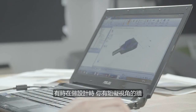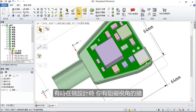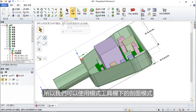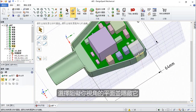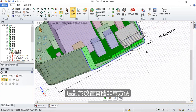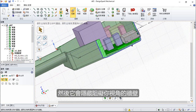Sometimes when making designs, you have walls that are obstructing your view of a component. So for instance here, we can't see the USB port properly in order to position it in the pin holes. So what we can do is actually use the section tool under the mode toolbar. And what we can do is select a face and it hides the wall that is obstructing your view of the object. And this is really handy for positioning items. So you simply click the part you'd like to see first once the section tool is selected, and then it will hide the walls for you.